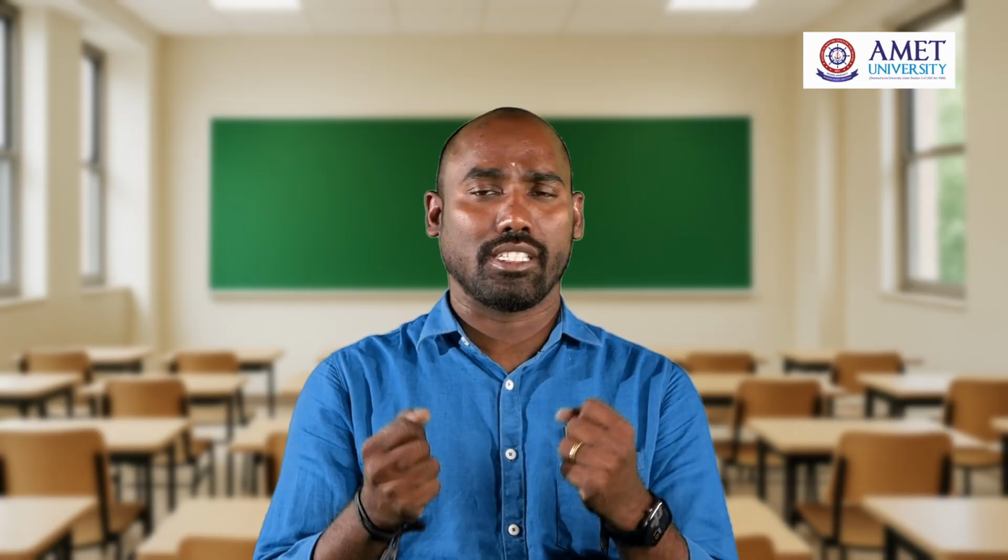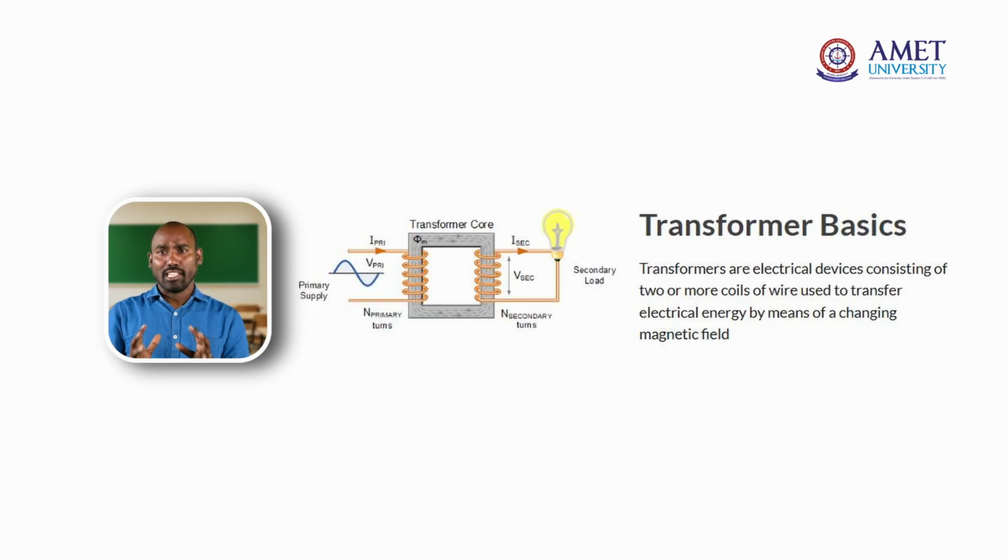This is about the transformer and its uses, and the necessity of a transformer. A transformer works on the principle of mutual induction. As you all know, what is mutual induction? If you keep two coils near each other and change the current in the first, primary coil, an EMF is induced in the secondary coil. If there are changes in the primary coil's AC current, it induces an EMF. We call this mutual induction.